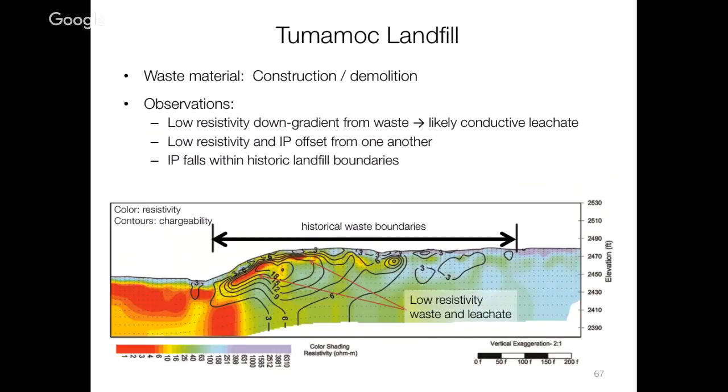Here's another landfill. I like this example, and we also have another whole case history on this, because this often happens. You're trying to get rid of your waste. Where do you do it? You want to put it in a hole. Where do you have a hole? Well, let's suppose you've got a valley of some sort. So you just drive the truck up to the end of the valley, dump it off, and off you go. But gradually, the valley fills up, and eventually the edge moves out there. With the passage of time, water percolates through here, and dissolved metal ions, leachate, can come out the bottom.